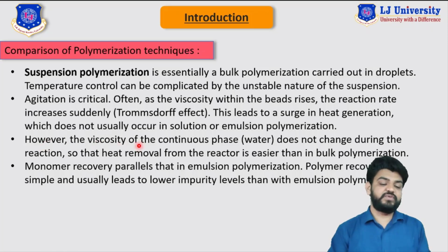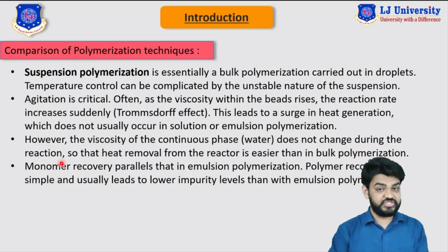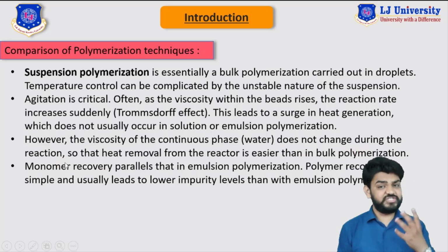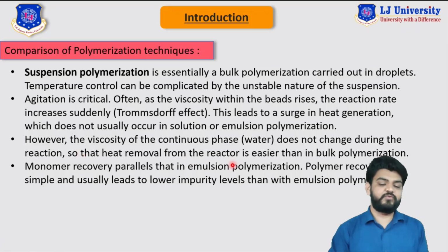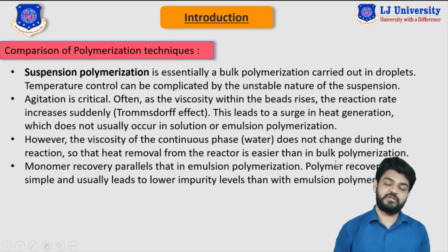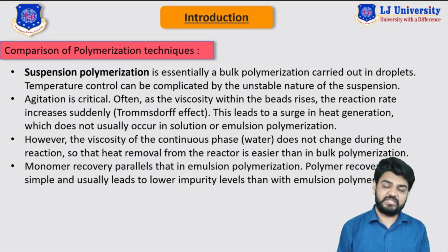Now, however, the viscosity of the continuous phase, that is your water phase, does not change during the reaction. So we can say that in suspension polymerization, the viscosity of the solution remains more or less the same before and after the reaction, so heat removal from the reactor is easier than in bulk polymerization. In bulk polymerization, as the reaction proceeds, viscosity continues to increase. But in suspension polymerization, the viscosity remains more or less similar to the initial stage, so we can easily remove heat from the reaction mass. So this is an advantage of suspension polymerization.